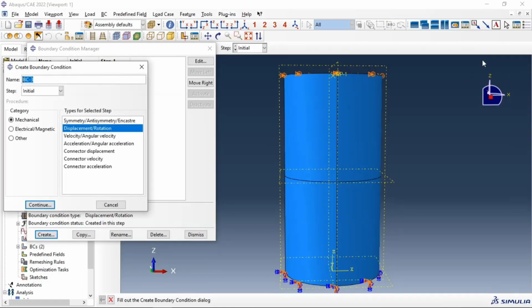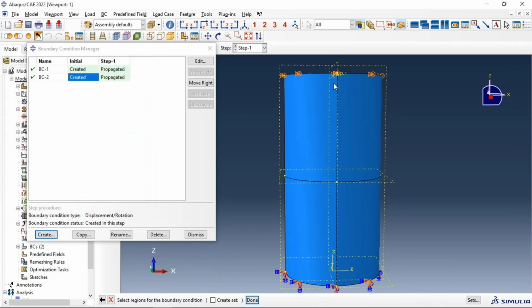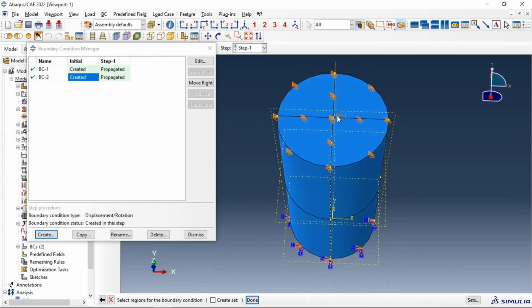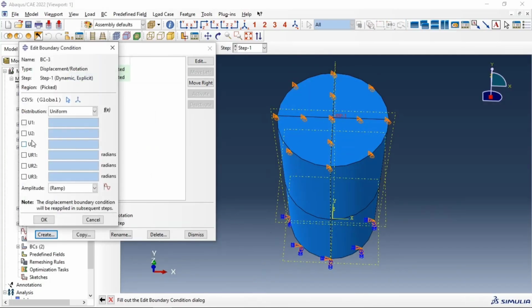I'm mentioning again, you can create an independent instance of the cylinder. The assembly represents the physical placement of the component within the simulation. Since only one specimen has been used, let's focus on this line. You don't need any additional positioning after we define the cylinder position at the center of the global coordinate system.